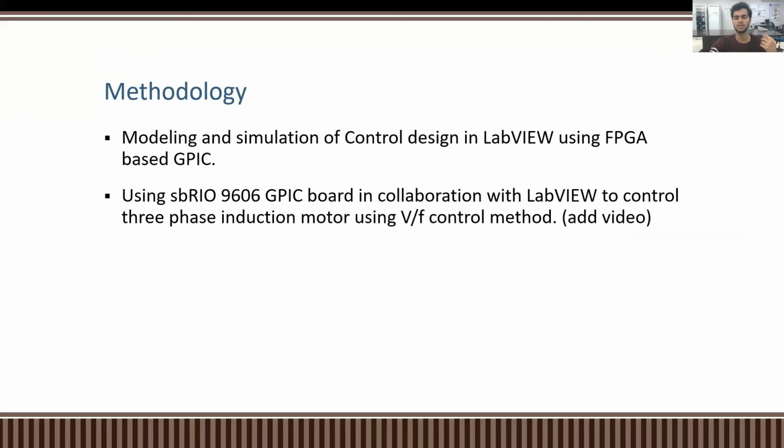The upper part, the FPGA-based GPIC, is just the control design, the modeling and simulation of all the control design in LabVIEW. And our board is directly integrated with LabVIEW to control the three-phase induction motor using the V/F method.